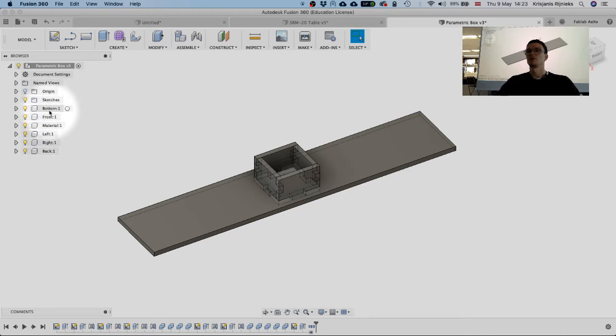And the difference between bodies and components is that, if you look at our project, it has this origin, this global origin object over here, which represents the axes and the planes. And we were designing these objects against this origin. But once we are creating components from bodies which are designed against this global origin, then in the component itself, the origin is actually copied.